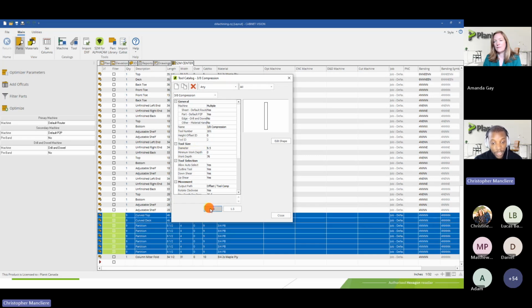So for example, if we talk in millimeters, if my tool is 9.5, I would say anything up to 9 millimeters will be acceptable. Half a mil will be fine, or else there's a big difference. So you might want to adjust it in CAD as well if it's constantly way smaller than what you think it is in the software here. So that's for the tool diameter.